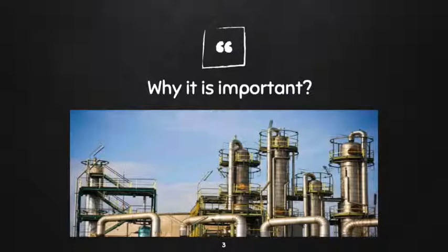Alkylation offers several key advantages to refiners, including the highest average quality of all components available to the gasoline pool, increased amounts of gasoline per volume of crude oil, and high heats of combustion. Alkylates permit use of internal combustion engines with higher compression ratios, and hence the potential for increased miles per gallon. Alkylates burn freely, promote long engine life, and have low levels of undesired emissions.